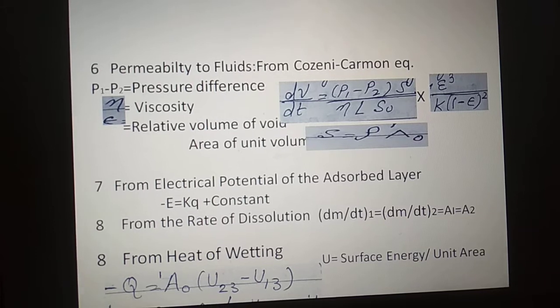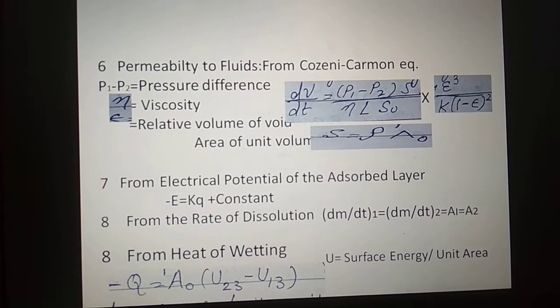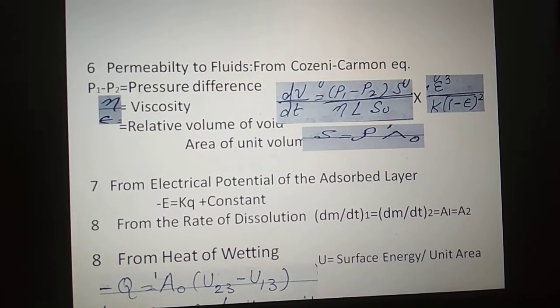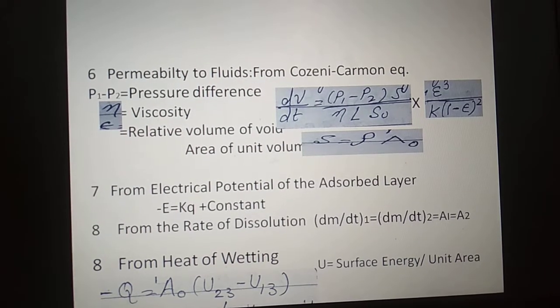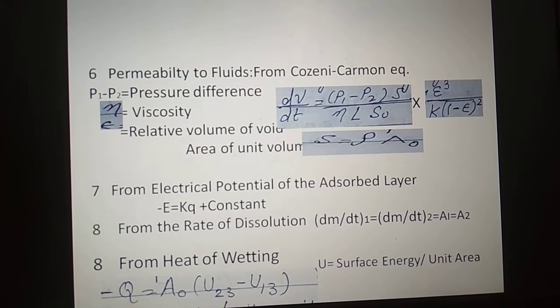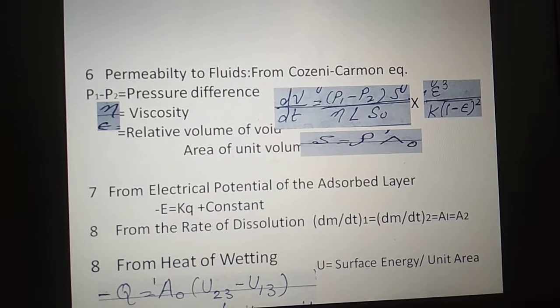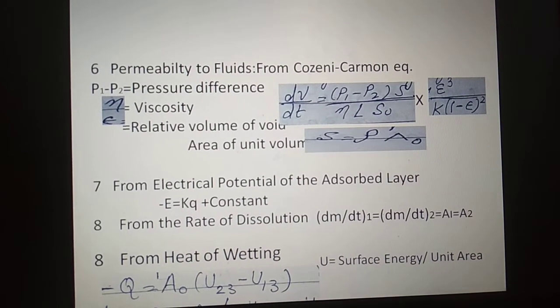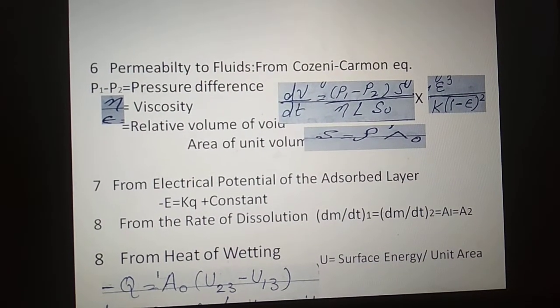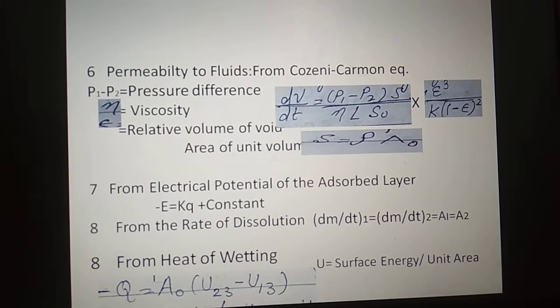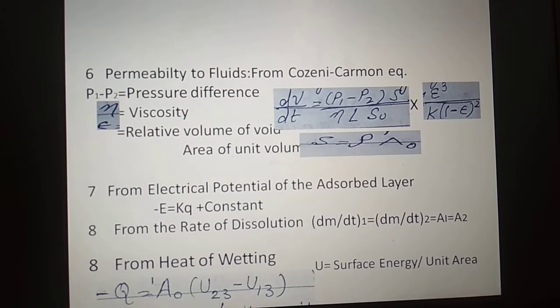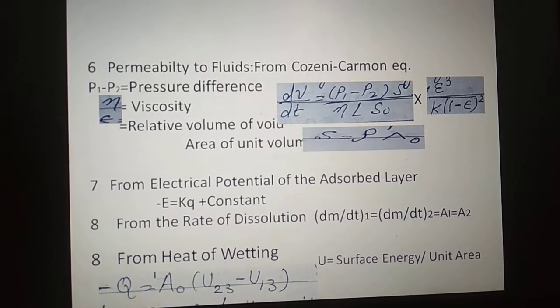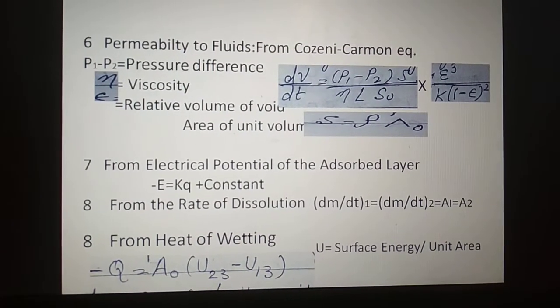Limitations. First, the plug must be of fibrous or compacted powder, but should not contain pores or voids with one entrance only. A pore is registered only if the fluid enters it from one side and leaves at the opposite end.